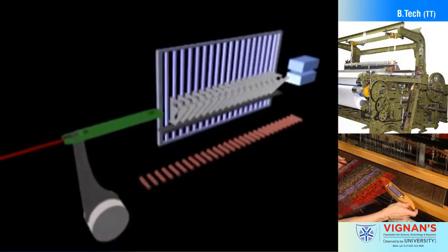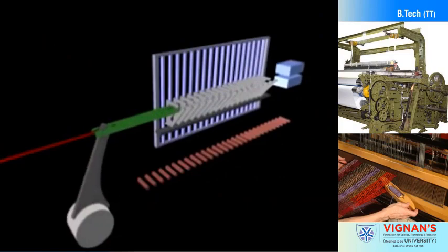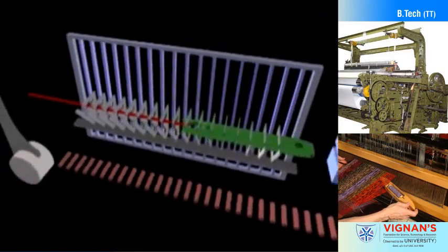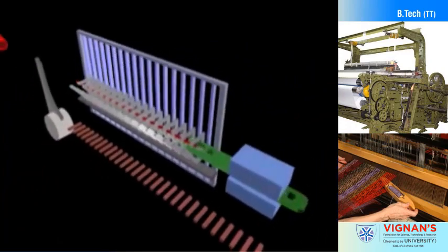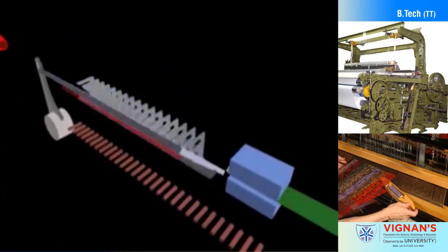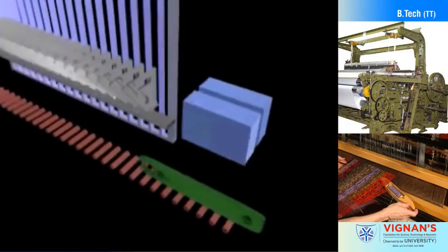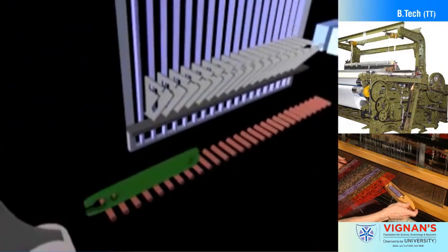A projectile is presented to the picking arm and is fed a yarn. It is then fired across the loom through guide teeth to where it is caught in a braking device. It is then returned to the picking station by way of a conveyor chain. Several projectiles are in use at any time so that rapid pick insertion can occur.